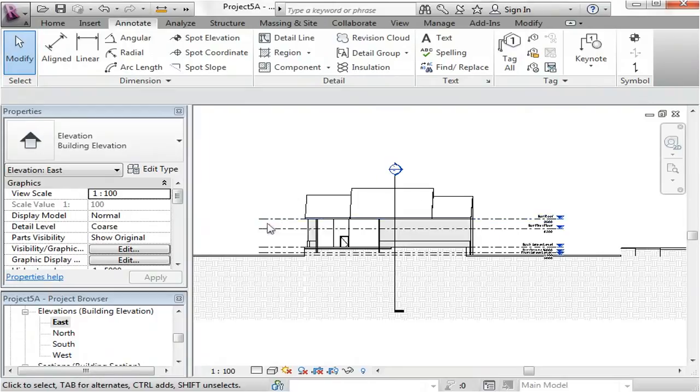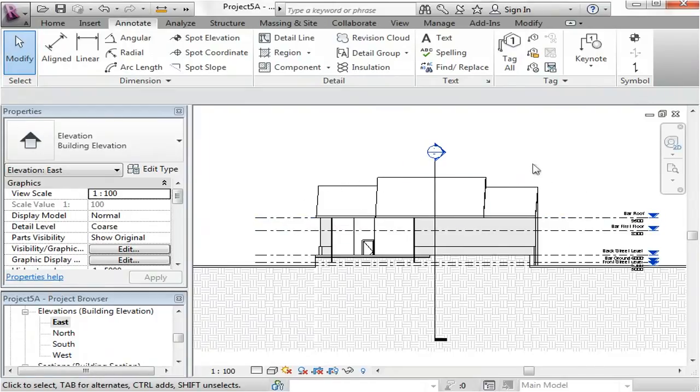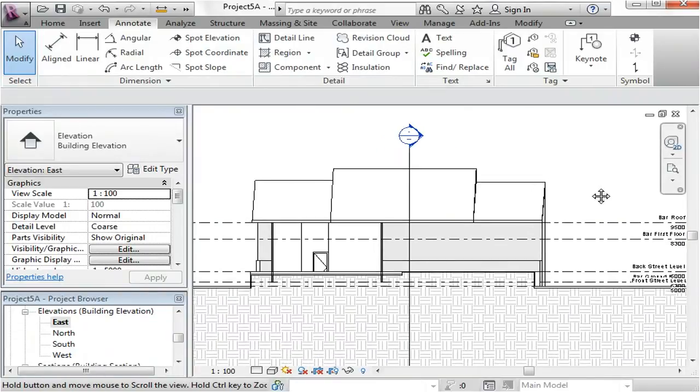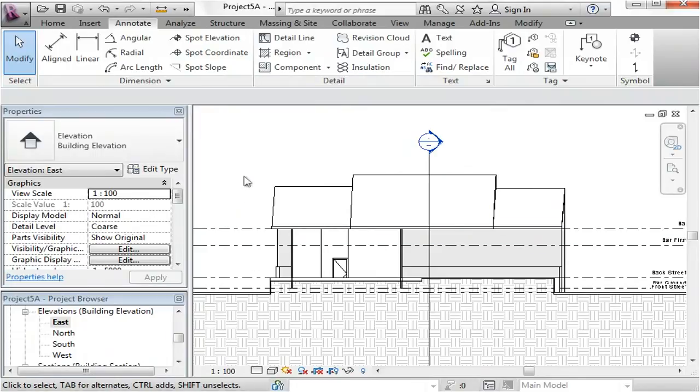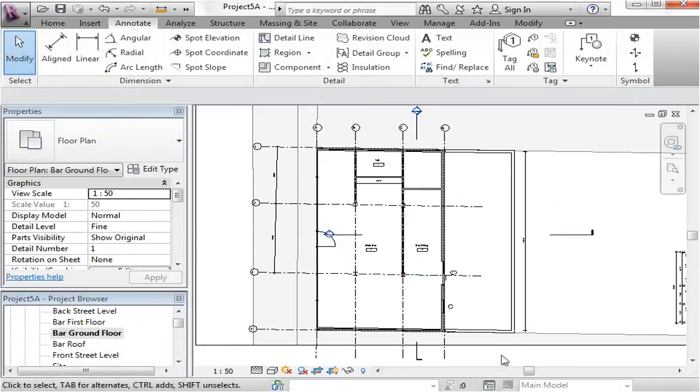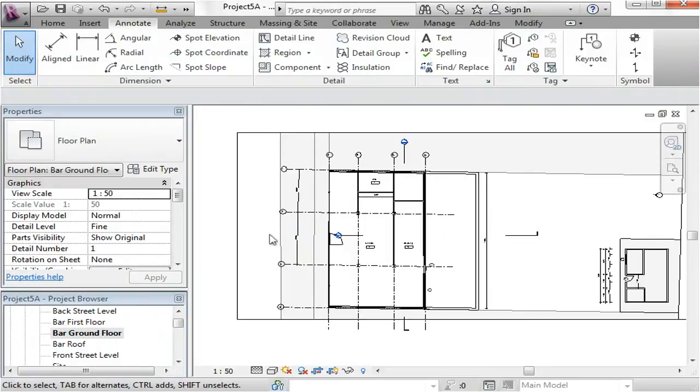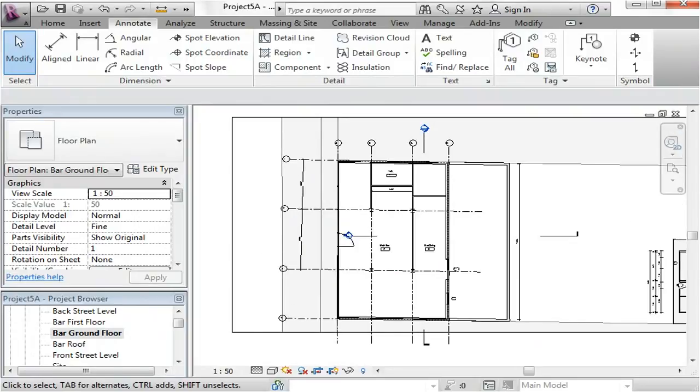Okay, so in the elevation I don't need to provide lateral dimensions. Keep in mind that in elevations and sections, you're probably more interested in heights, so that's when you start to dimension more heights than anything else. Okay, I'm just going to move on to annotation, and I'll leave you to finish off the dimensioning where it's needed. Make sure that dimensions appear on all drawings and not just one.